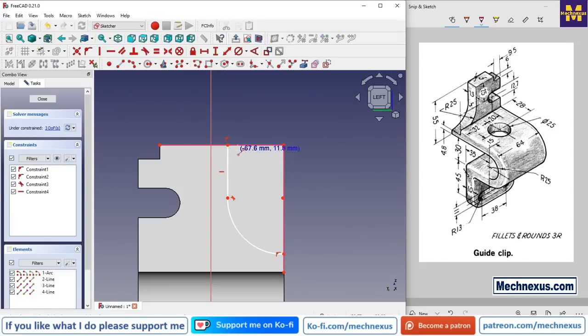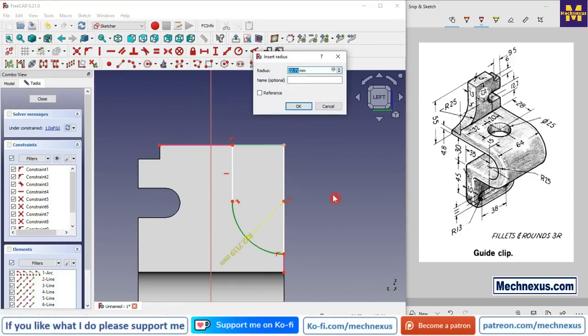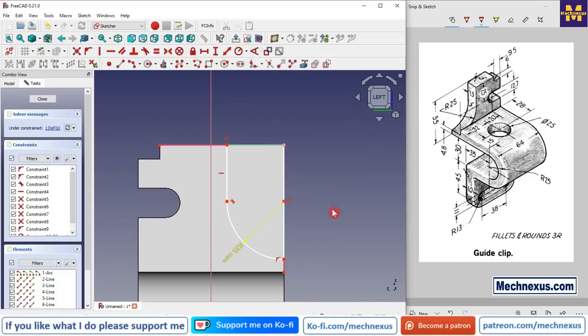Now we will close our profile, and this arc will have the coincidence relation with the line, and we will select the arc and click on the radial dimension and give it 25, and this center is 25 from the top, because we can see that its slot center and this center are in the same line.